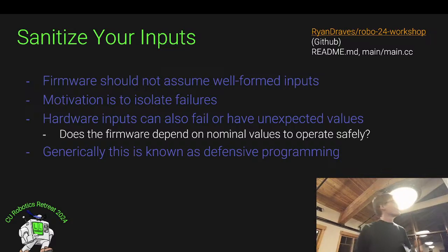Okay, so my first topic here is to sanitize your inputs. In general with software, and definitely true with embedded systems, you should not assume well-formed inputs when something comes into your device. Whether this is from the client or from the hardware, the signals that you're reading out, it's never a good idea to just blindly assume that what you got is good and run with it, right? And the motivation behind this is that when you have an error, say some corrupted request was sent, you don't want to have a failure be propagated from one part of the system to the other.